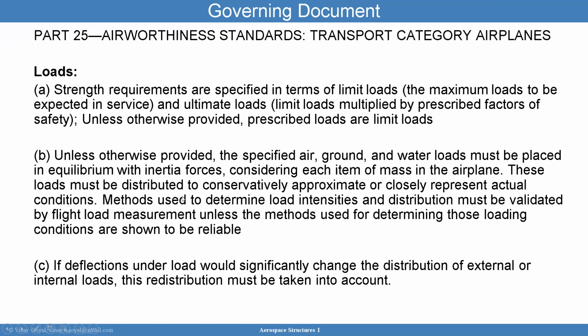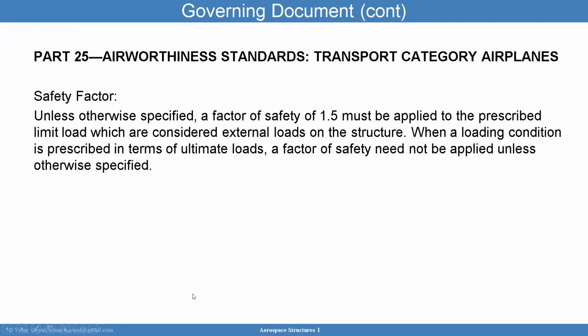In other words, you want to apply the loads as close as possible to what the airplane is going to experience in flight, and analysis can be very valuable to show that you are in line there. If deflections on the loads will significantly change the distribution of external or internal loads, this redistribution must be taken into account. In other words, if there are large deformations, the loads can change distribution, so you have to account for that somehow in the test.